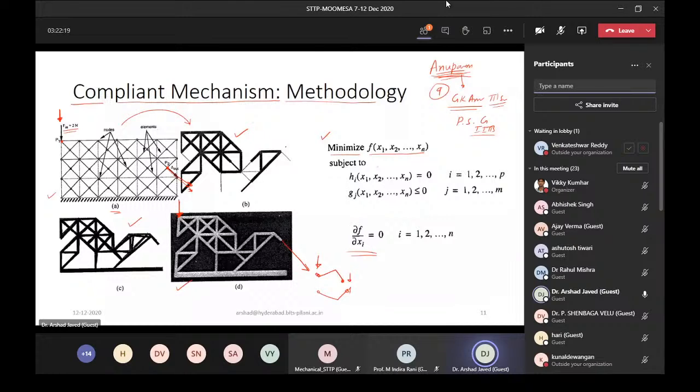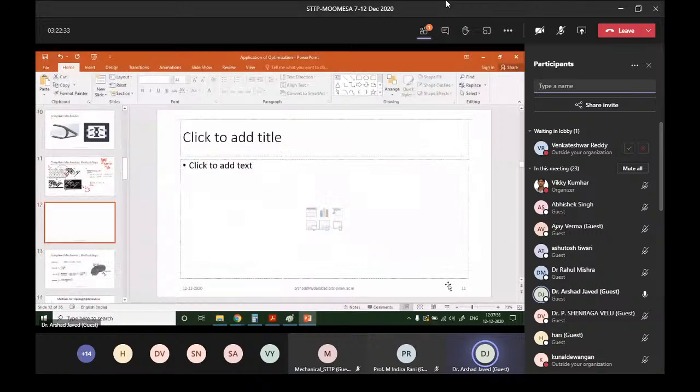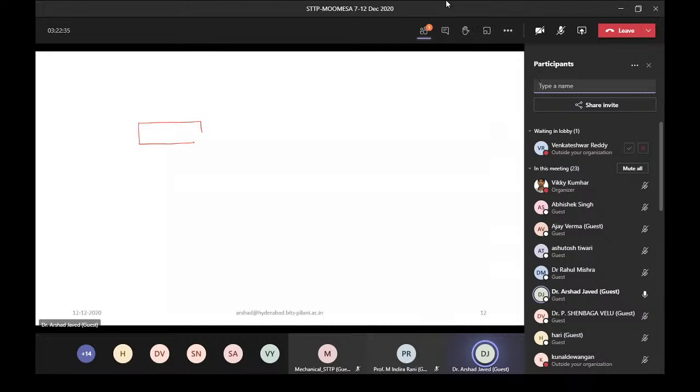Also, people have tried to find out some material which is called negative Poisson ratio material. What is that negative Poisson ratio material? Let us see what is negative and how they have done it. Normally we know that if you stretch a sheet or a metal bar in this direction, if you employ the force in this direction, what will happen? It will compress in the transverse direction. Since the material mass is fixed, when you stretch in this direction, it will be reduced in the width and elongated. It is like this.